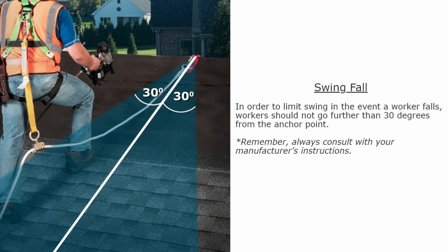Swing fall. In order to limit swing, in the event a worker falls, workers should not go further than 30 degrees from the anchor point. Remember, always consult with your manufacturer's instructions.